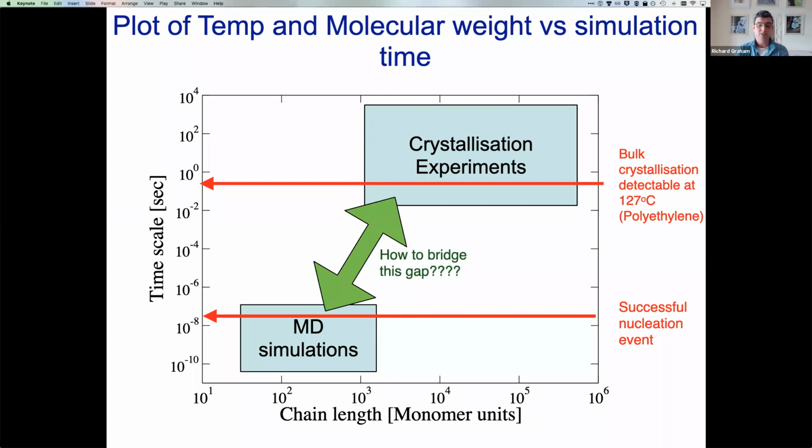What's interesting with flow-induced crystallization is that once you add flow, you make the bulk crystallization sufficiently favorable that it then starts to dominate. So when you do a similar experiment in a flow-induced case, the distribution of crystals that you see is different each time you repeat the experiment. So you're not seeing heterogeneous nucleation. When comparing with experiments, people typically assume there's a background amount of heterogeneous nucleation that appears the second you cool the material down. And then the additional nuclei that you see during flow are the result of genuinely random bulk homogeneous nucleation. That's generally how it's tackled.